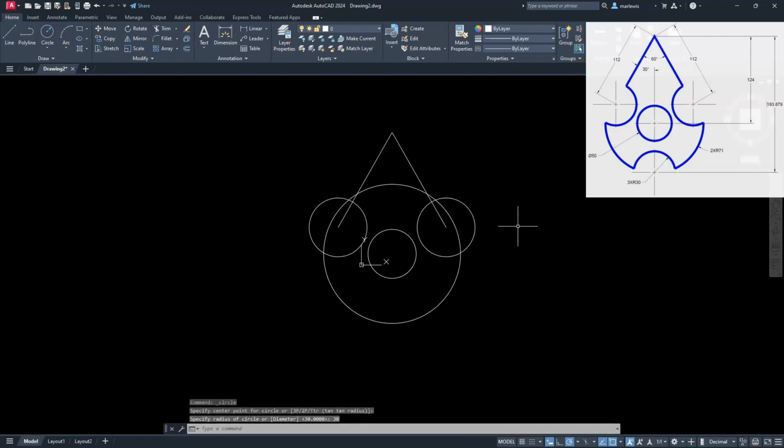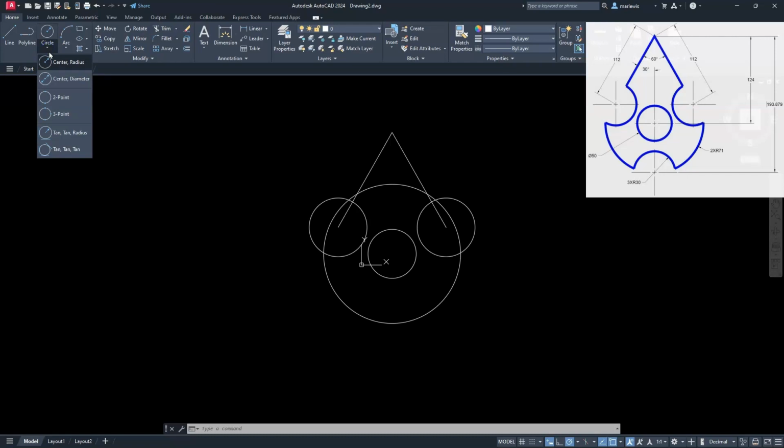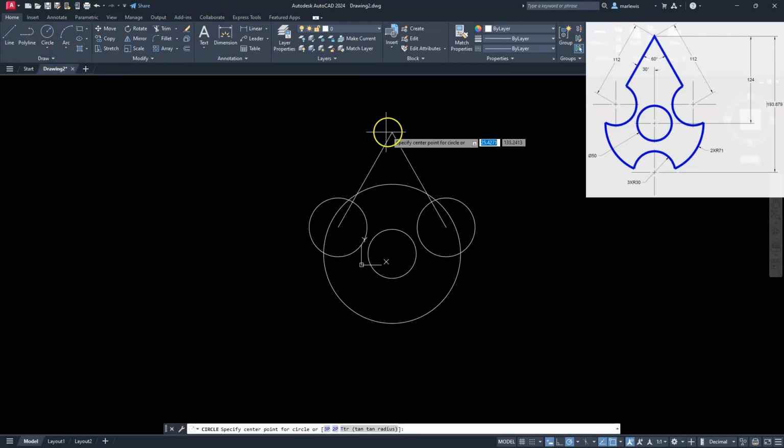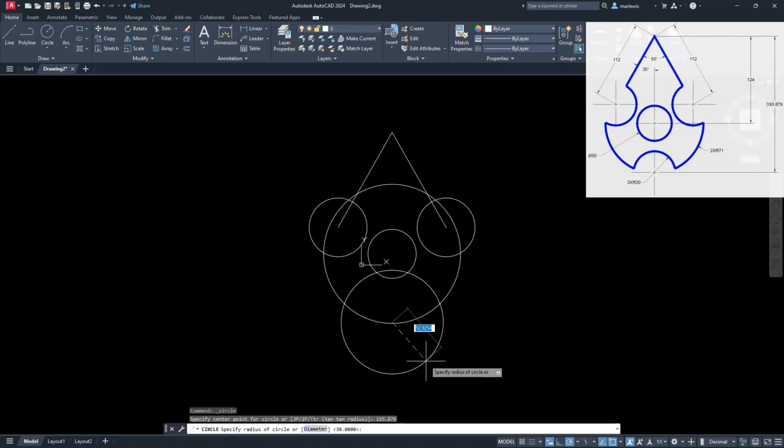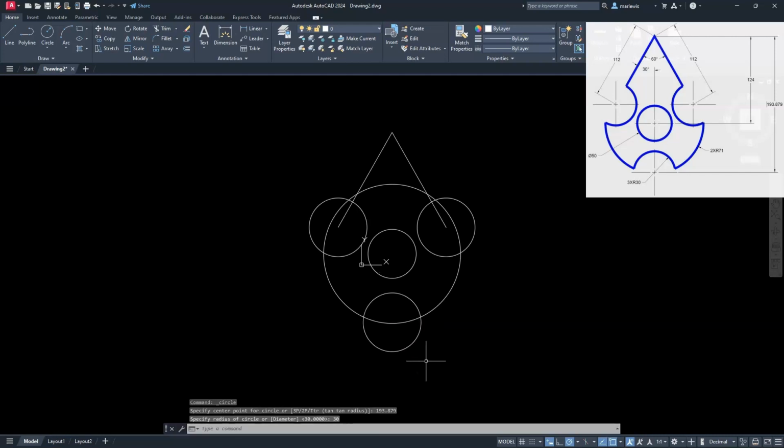If you want, let's go ahead and create our other line, and this one has a kind of weird number on it. It goes down a distance of 139.879. So that's easy enough for us to create. So circle, center radius. I want you to touch this endpoint and then get the tracking off of it, right? So I have my snap tracking turned on. Once I got the green tracking lines, I'm just going to type in 139.879. Go ahead and hit enter. It should place that circle somewhere at the bottom there. And then this one has a radius of 30.